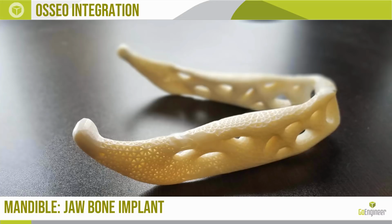So what we see on our screen right now is a mandible or a jawbone implant. I have 3D printed this using our PolyJet machine because of the fine, intricate details that we see on our screen. Another benefit and another reason why I did it this way was we have dissolvable support, so that I don't have to actually manually remove all the support from those lattice structures. I can just throw it in a tank and dissolve it away.